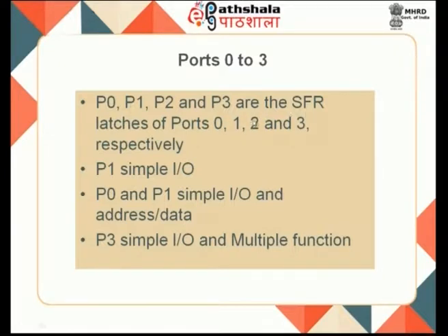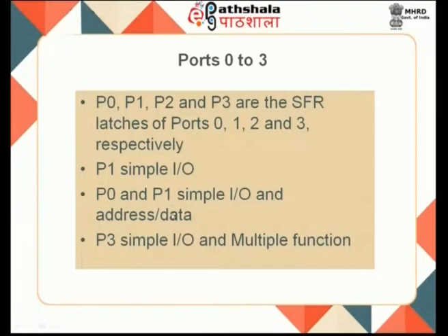These are all special function register latches: P0 to P3 are SFR latches for port 0 to port 3 respectively. Usually port 1 is a simple IO port, whereas P0 and P2 are simple IO and address bus and data bus. That means it acts like a multiplexer. I can use P2 and P0 together for address, and data can also be read over there. So, P0 and P2 together will be used for address and data communication, whereas P3 is simple IO and multiple function. The other special functions can be interfaced through my port 3.